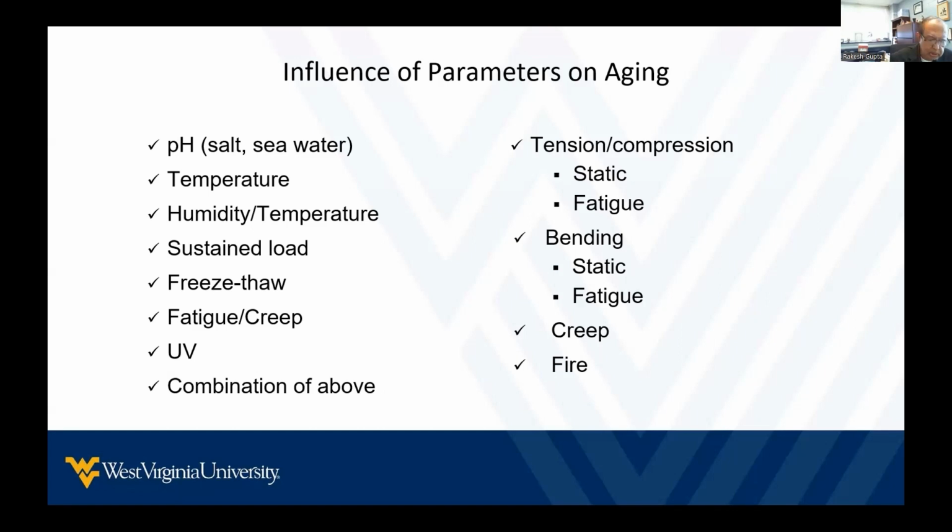Surprisingly, moisture turns out to be a very harmful agent by itself. It causes physical changes, such as lowering in the glass transition temperature, and what that does is to plasticize the matrix, and you can have significant changes, 20 degrees C lowering in the Tg with 1 or 2% concentration of moisture in the polymer. This affects the temperature at which the composite can be used.